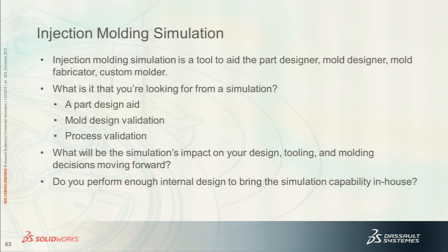I do various types of mold design validation, process validation, but I also use it heavily as a design aid for the parts right up front. Again, that would be like the new add-in SolidWorks Plastics. I currently still use SimpoWorks, which has a couple more functions that SolidWorks Plastics doesn't have. SolidWorks Plastics gives you fill and pack data at the